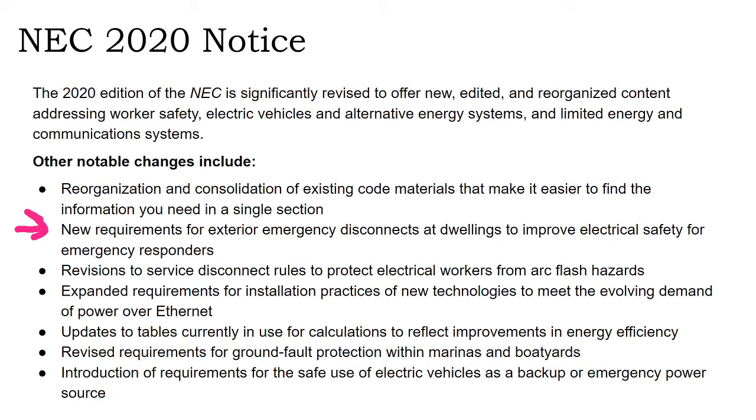But to some extent, you get value for that. I mean, it is nice when installed professionally to have this knife switch disconnect to disconnect all things. Doesn't have to be a knife switch. Some utilities called a knife switch. Where that comes from, we'll get into in a minute. Sometimes knowing code and being able to educate the inspector on these things helps you get out of local jurisdiction requirements that aren't actually in code.